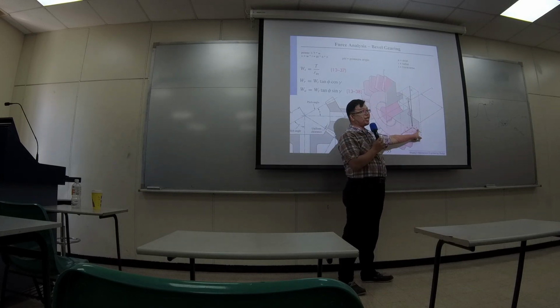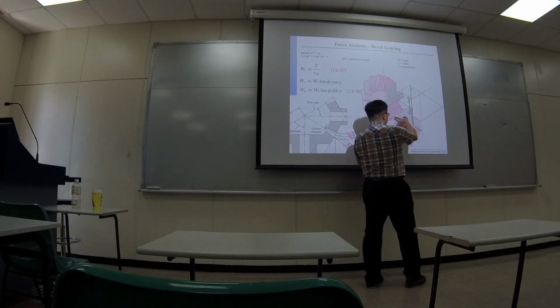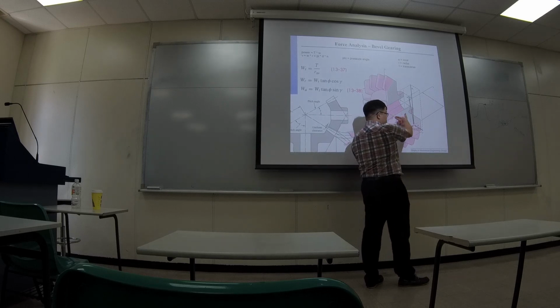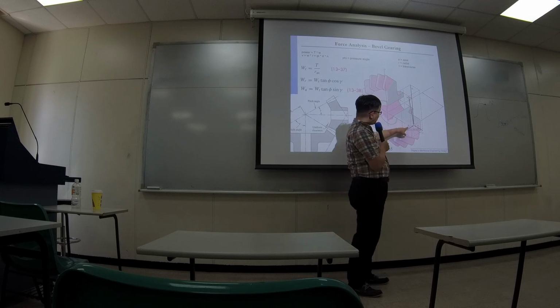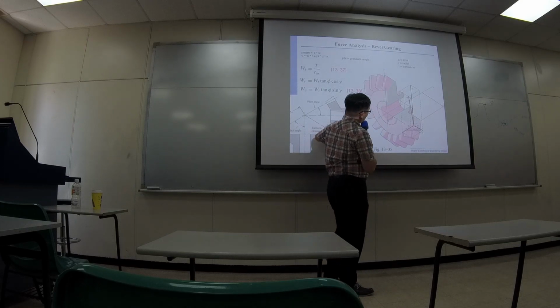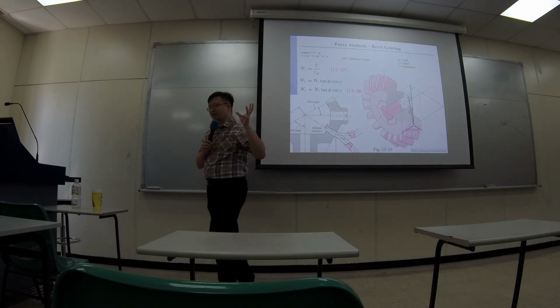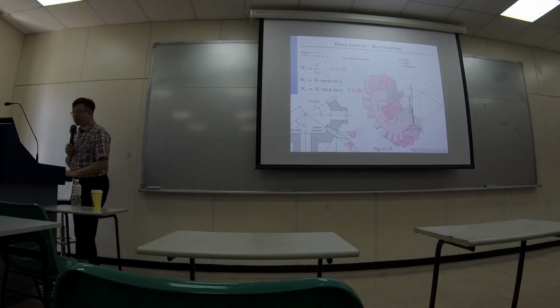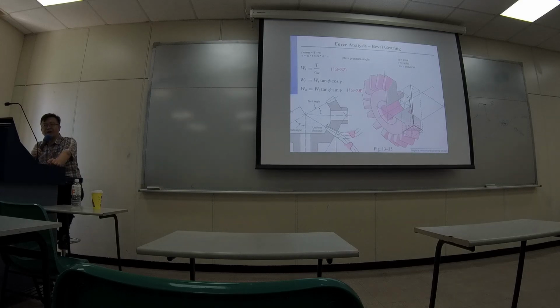WR represents the radial component, so basically the direction that is parallel to the radius. And the other one, WA, represents axial, the direction along the center axis of this gear. So for spiral gears, if you try to study the force applied to the teeth, you always need to compute the force components along all three directions.